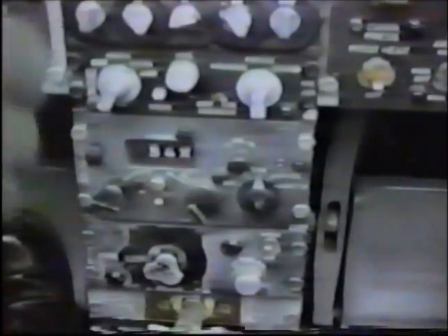Finally, you want to check the TACAN. To accomplish this, you can either do the Flight Director System TACAN check described in 51-38, or you can do the TACAN self-test, which is simple and efficient and is used by many IPs. To accomplish the TACAN self-test, tune in the TACAN channel on the field and listen for the TACAN identifier, which will signal once every 35 seconds.